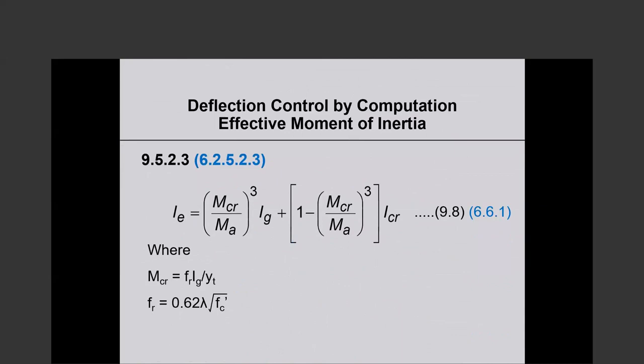There is one question: is long-term deflection automatically computed in the result of an FEA model? You have to see which software you are using. Most of the software will basically do the same thing that Dr. Ghosh said. They will estimate it. It's not calculated. You cannot calculate a long-term deflection just like that. It will be estimated based on different formulas, and you have to see if the software does it automatically. Most of the software don't do it automatically. You have to check a button or something to calculate long-term deflection. So be sure about that.